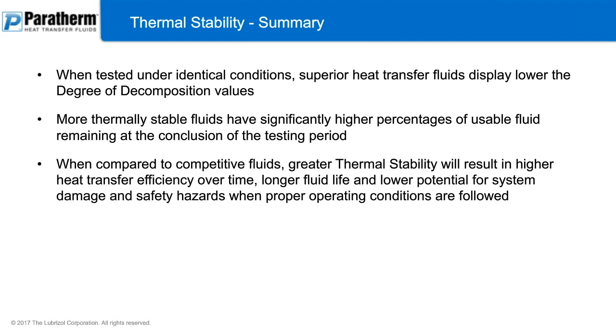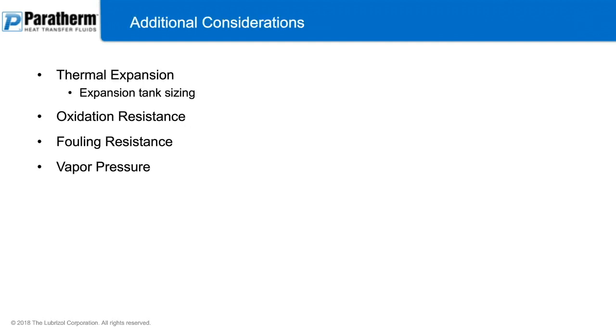Request a thermal stability analysis between two fluids that you're considering. That'll really give you a great idea on what fluid may be better than the next, or what fluid chemistry in general might be better than the next. Additional considerations, thermal expansion, oxidation resistance, fouling resistance, and vapor pressure are also key benchmarks.